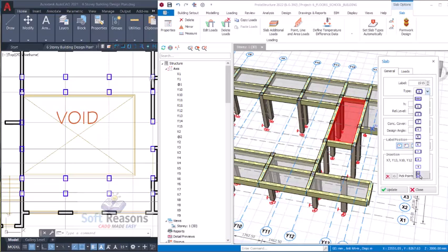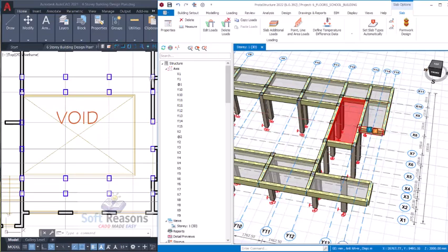We'll be using slab 12, which is only supported by one side, but in this case, this particular slab is supported by 3 sides, so it's not necessarily going to be a cantilever slab, just as I've said earlier. So this is what I wanted to show you. It's supposed to work with slab type 3, supported by 3 sides, but ProtaStructure will take care of that. Click here to get rid of that, right click and then click on property again.